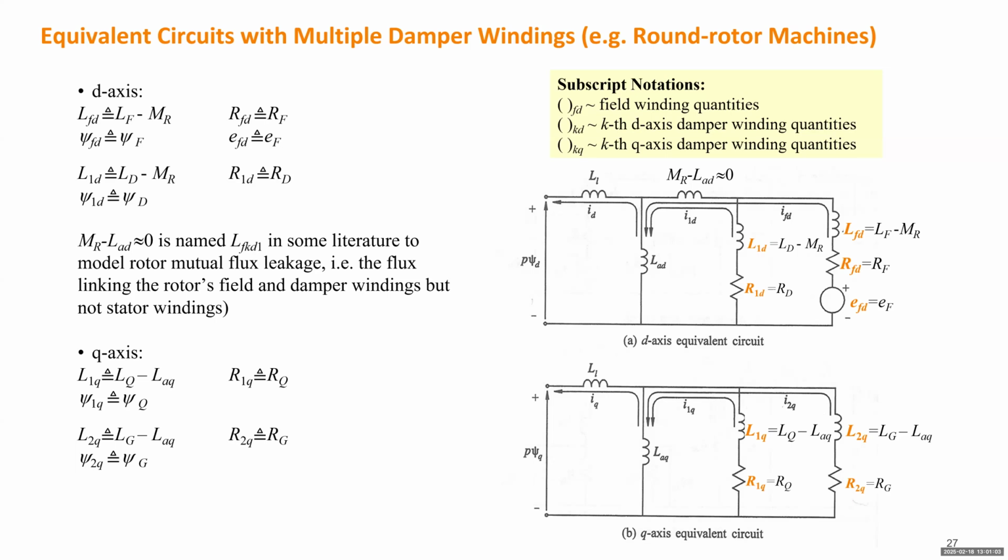We're going to show that the equivalent circuit came from those two circuits by simplifying some parameters. For a transformer, it's also not convenient to have two circuits, one for the primary winding and the other for the secondary winding, which are isolated. So you want to connect the two windings into the same circuit. Having just a single circuit to do the study is always more convenient.